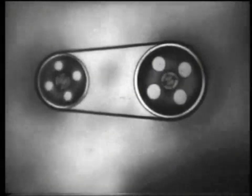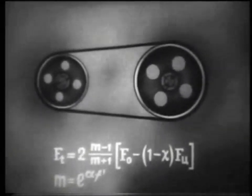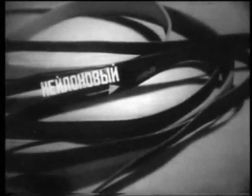The criteria for the operability of the belt transmission are the traction properties and durability of the belt. The traction capacity, characterized by the circumferential force, increases with an increase in the coefficient of friction and the angle of wrap. Therefore, friction coatings of flat belts appeared, as well as V-belts, gears with guide rollers that increase the angle of wrap.